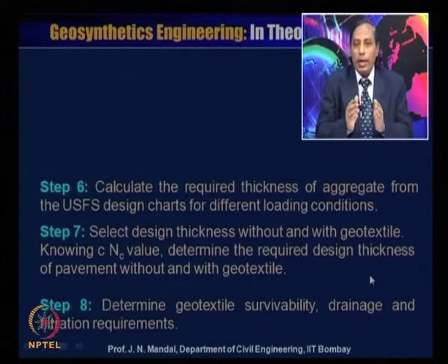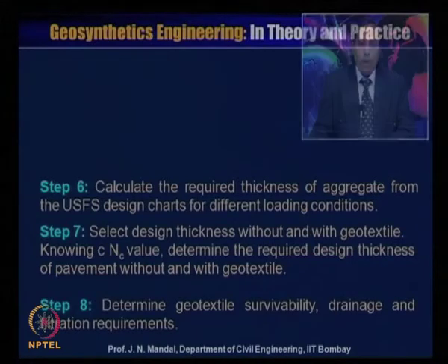Step 6, calculate the required thickness of aggregate from the USFS design chart for the different loading conditions. Step 7, select the design thickness without and with geotextile, knowing the value of C into Nc. Determine the required design thickness of pavement without and with geotextile. Step 8, determine geotextile survivability, drainage and filtration requirements.